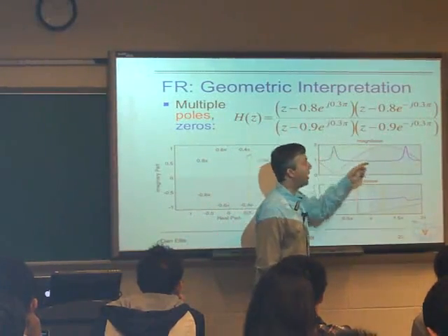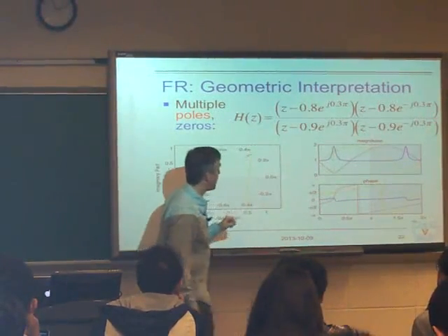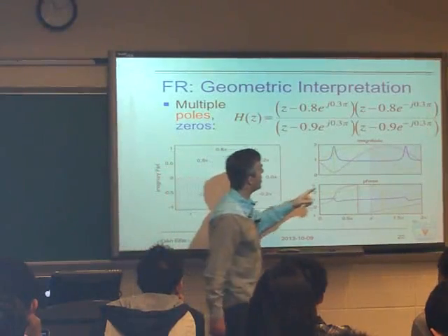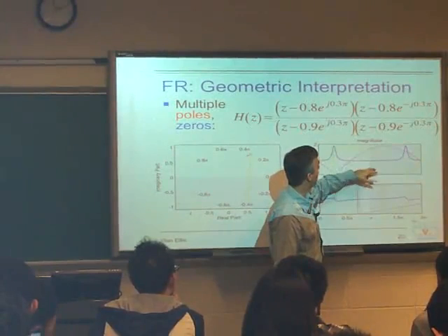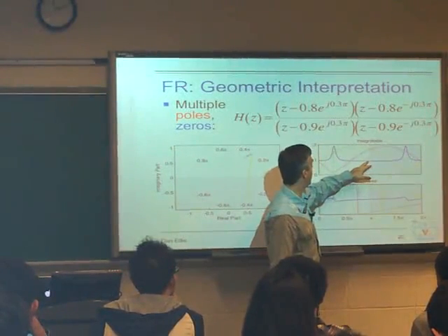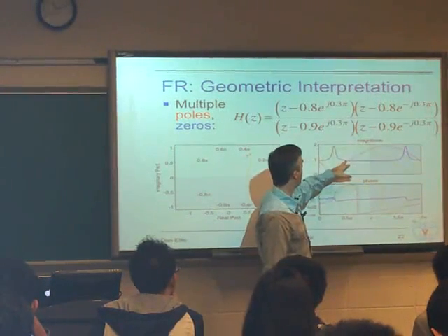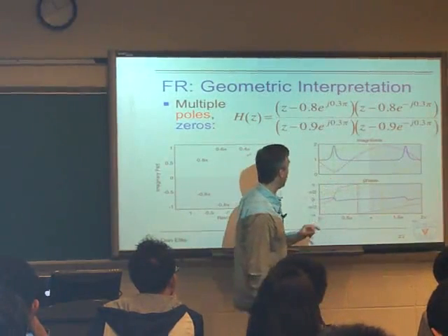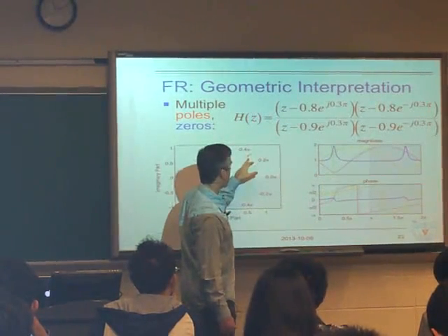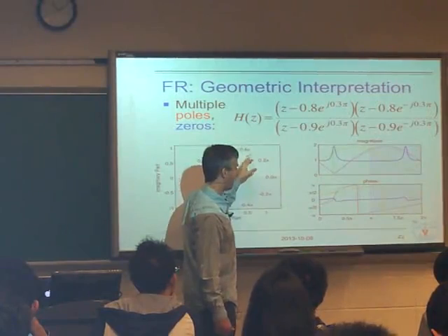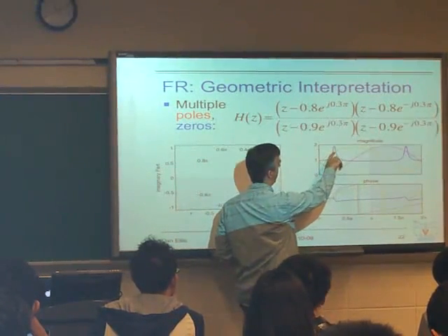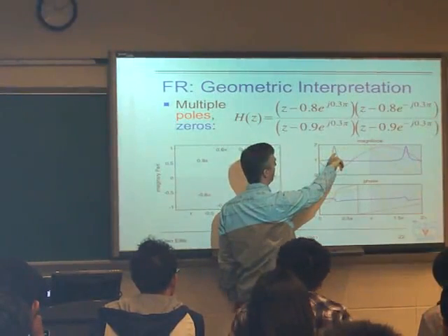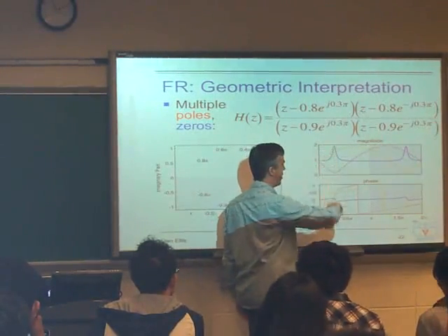The thick blue line is the overall magnitude response of this system. And so what happens here is, out here, those are about the same, those are about the same. We multiply them all through, we get a number which is about 1. The only place where they're not all balancing out nicely is right here around this point where we're close to the roots here. Over here, the orange is 1.5, the green is 1.45. Their ratio is about 1.